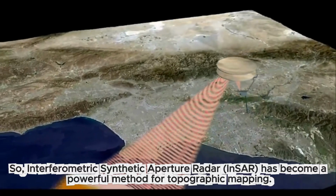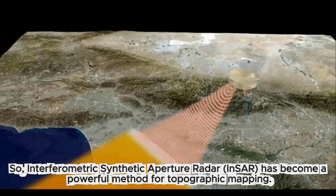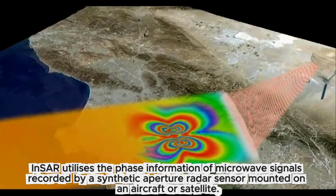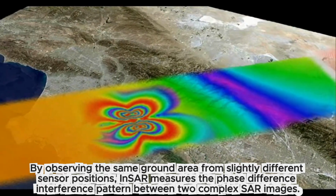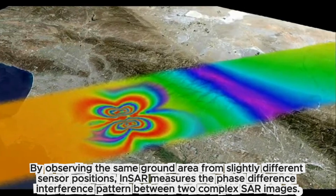So, interferometric synthetic aperture radar, InSAR, has become a powerful method for topographic mapping. InSAR utilizes the phase information of microwave signals, recorded by a synthetic aperture radar sensor mounted on an aircraft or satellite. By observing the same ground area from slightly different sensor positions, InSAR measures the phase difference, or interference pattern, between two complex SAR images.